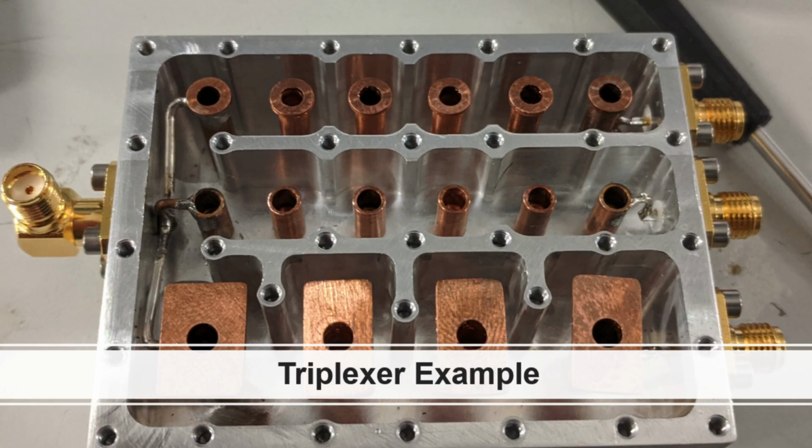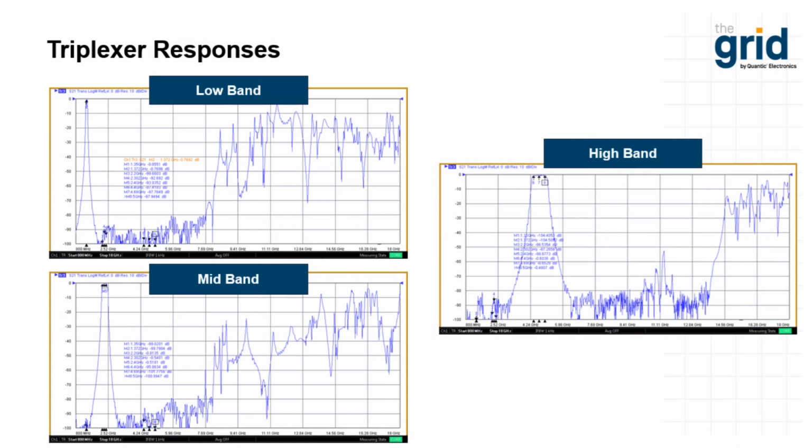So that would be the mid band. So the mid band would be the top channel, the low band would be the bottom channel, and the high band would be the middle channel in this particular example. It doesn't have to be that way. They could be rearranged, obviously, but that's the way it is in this example. So shown here is the frequency response of the triplexer. The upper left is the low band response.